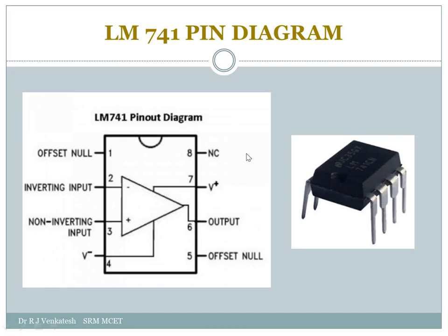You give the positive voltage to the non-inverting terminal. So when the input is given to the negative terminal, it is called the inverting input, and when the input is given to the positive terminal, it is called the non-inverting input. The output is taken from the 6th pin of the IC, and the other three pins are not in use, so we are not using them for amplification or any other arithmetic operations.